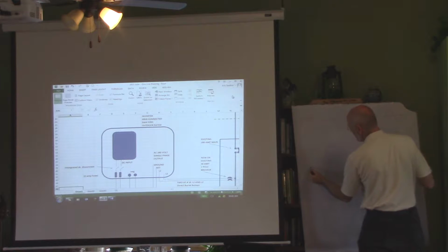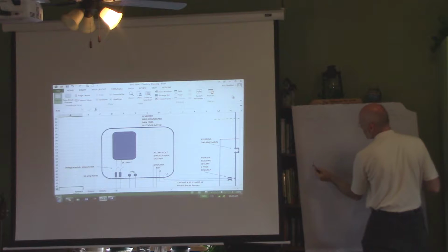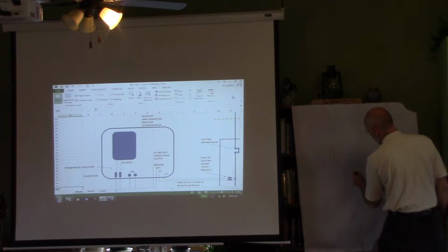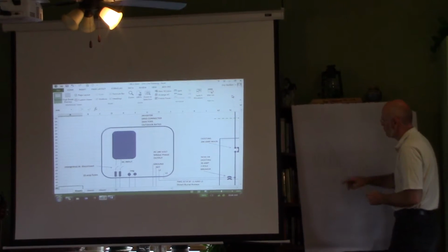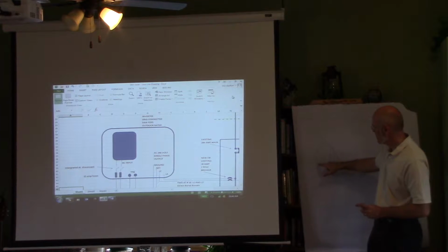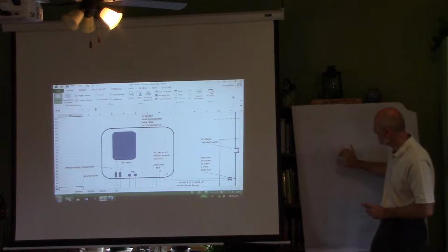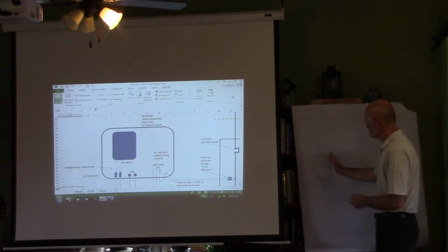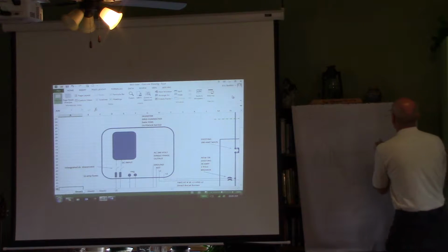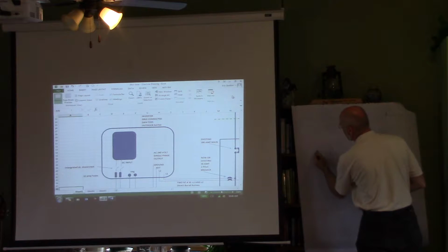So what the inverter does, and I'll make a big view of it here, is it tries to make that shape by creating little pulses. You see the sine wave showing up? This is a simplification of what's going on. But that inverter is turning on and off thousands of times a second and producing different little chunks of DC power. Very, very fast. And it looks like a sine wave. And because it's producing these little pulses when it wants to, it looks at the utility and says, I need to produce this moment of power right there. And that's what it cranks up, is it cranks up that little piece.